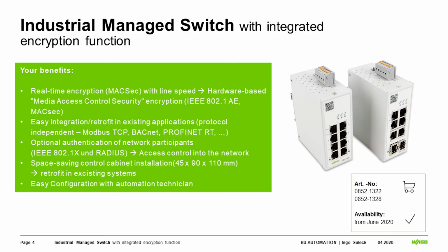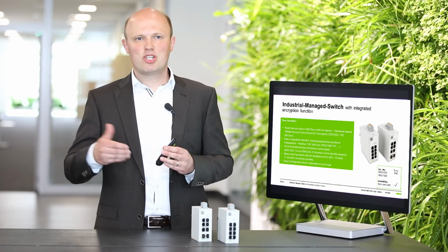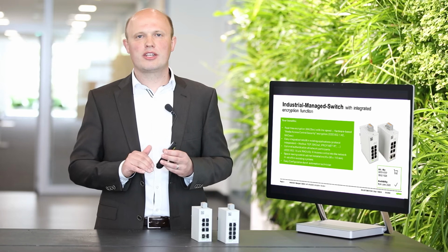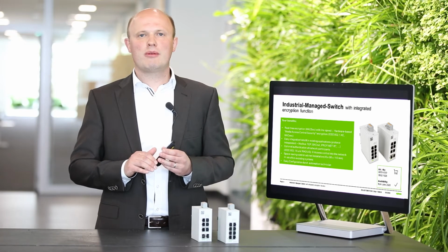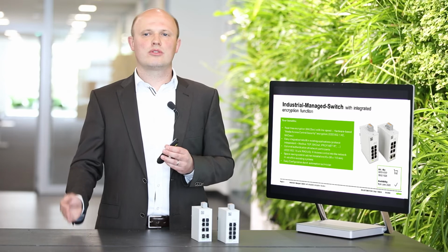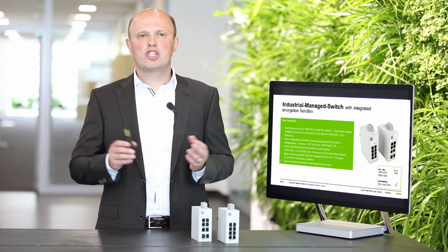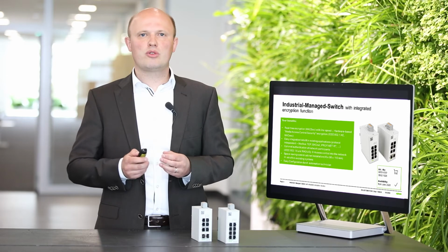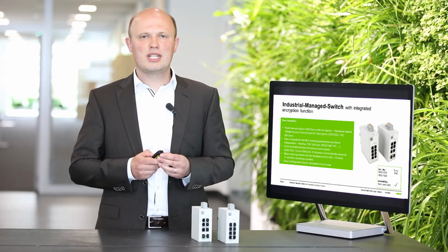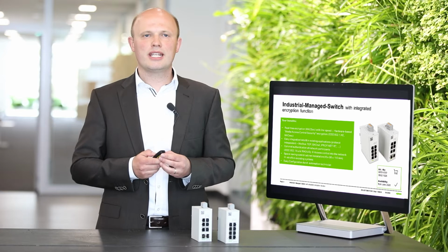A second very important point is, for example, if you have a Modbus application or a BACnet application, and this application is working over layer 2. If you use our MAC security encryption, you don't need to worry about changes in your application. You can switch your application directly to the secure link without changes. That means you can bring more network security into your network easily. You only must change the equipment, the network switch.